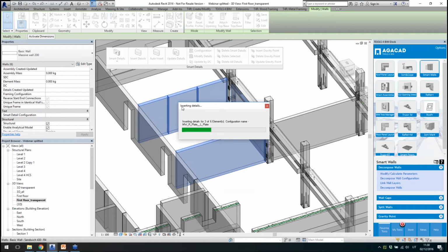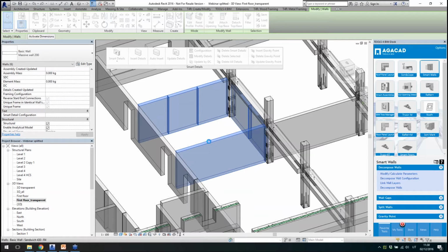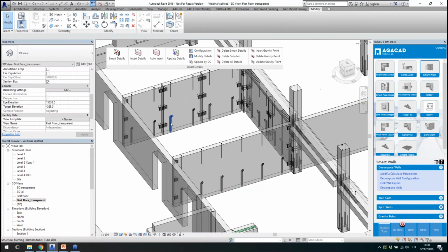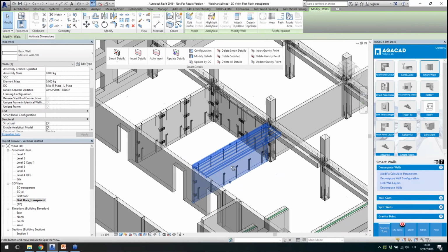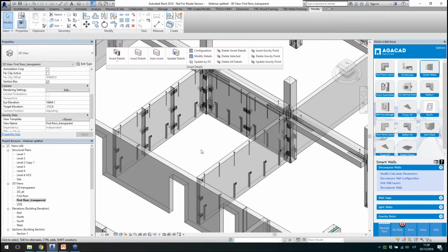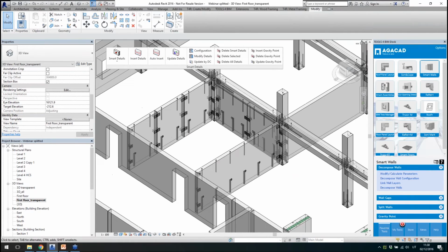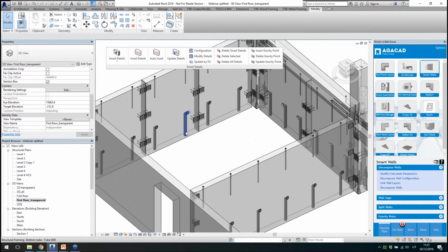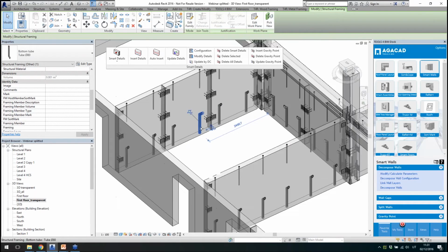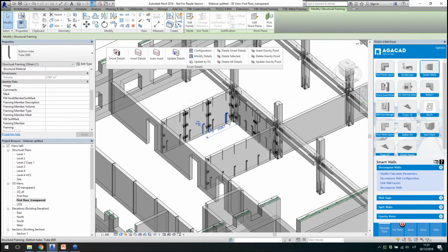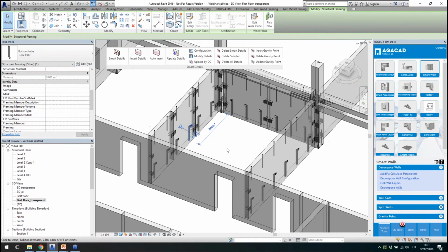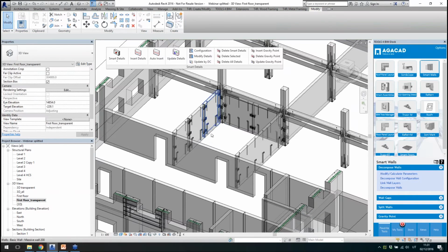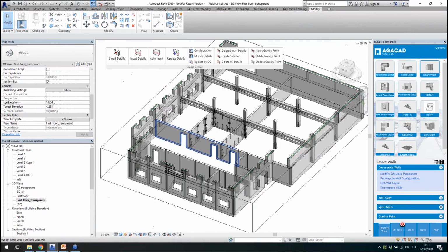So again, if it's based on the rules, it works for different sizes of panels, right? Because if I define the maximum spacing for these elements, then for this wall I will have just more of these elements and so on. And you can, of course, insert just the details you need, then move them according to the situation easily in Revit. But anyway, it's much easier to insert all of the details in all these possible ways.